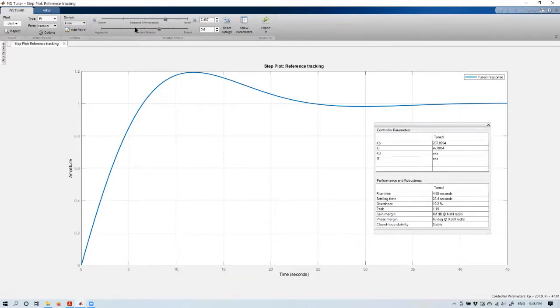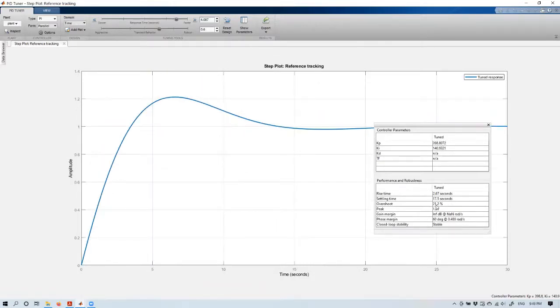All right, at the bottom here, with the bottom sliding bar, you can change the transient behavior of your system. You can make it more robust or more aggressive. In general, when you make your system respond faster, the overshoot may become larger, which may violate your requirement. For example, if the current overshoot is about 20%, and you make your system a little faster, the overshoot will increase.